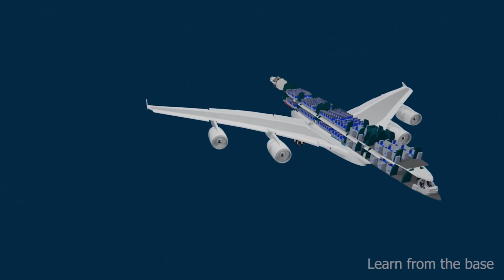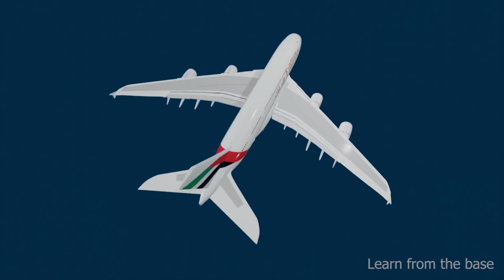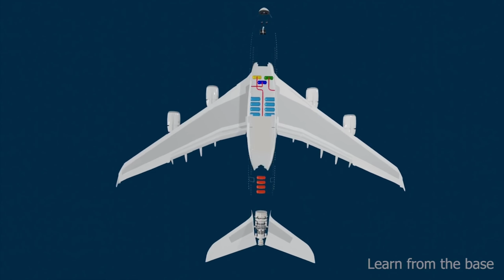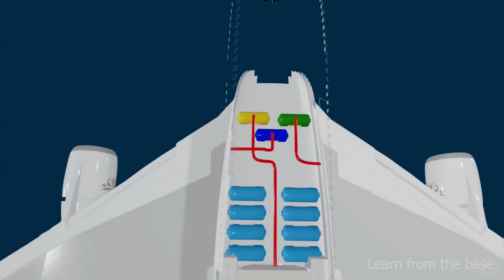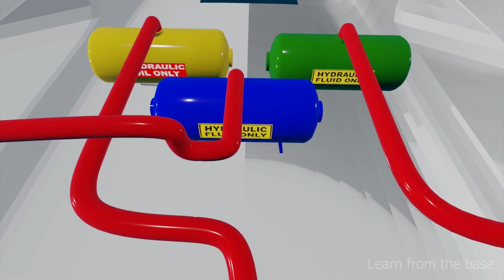The moving parts of the aircraft, such as doors, landing gears, flight controls, etc., are heavier in size and weight, so they need more power to operate. So the hydraulic system is used to operate the heavier parts of the aircraft. There are 3 hydraulic reservoir tanks: green, yellow and blue. The green reservoir is for landing gears, normal brakes, engine 1 reverser, and yaw damper 1. The yellow reservoir tank is used for nose wheel steering, alternate and parking brakes, cargo doors, engine 2 reverser, and yaw damper 2. And the blue tank is used for the emergency generator.